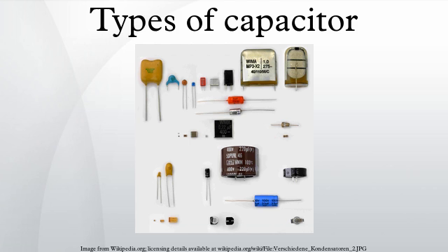Supercapacitors also experience electrolyte evaporation over time. Estimation is similar to wet electrolytic capacitors. In addition to temperature, the voltage and current load influence the lifetime. Lower voltage than rated voltage and lower current loads, as well as lower temperature, extend the lifetime.